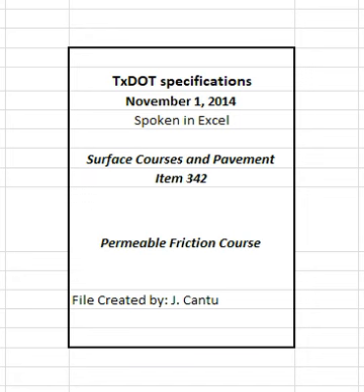Table 5. Testing frequency and mixture production tolerances. See table in specifications. 1 only applies to mixture produced for Lot 1 and higher. 2 Aggregate gradation is not allowed to be outside the limits shown in Table 4. 3 To ensure the binder content determination excludes fibers, add the recycled binder content to the flow meter readout when the asphalt mass flow meter is used to determine binder content.